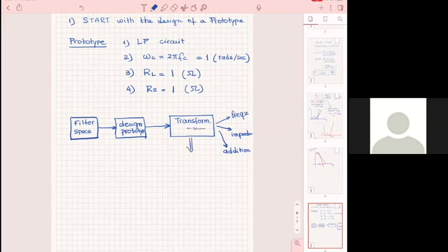Then you have produced an RLC, but a complicated RLC, all right? Because you're not going to have only one R, one L, and one C. As you see, depending on how your filter wants to be, you may have many stages. But then it's going to be a multi-stage RLC. And then after you have that, now you want to go and realize it.